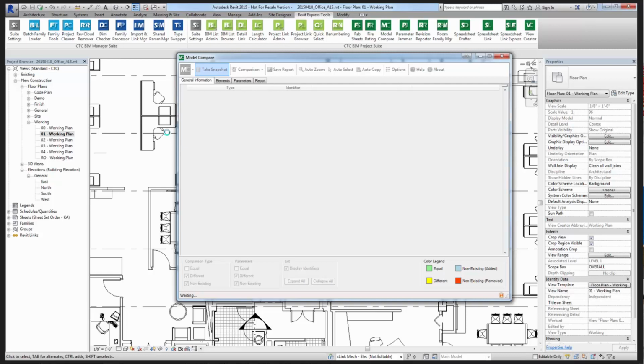One other thing I noticed: when that particular message pops up, make sure that you're not opening your models detached. If you do open a model detached, that's fine, but save it someplace. You actually have to have a file name on the file so that Model Compare understands what's going on. I did this earlier today: I opened detached and failed to save it. An unnamed file can't be used with the snapshot feature. You have to save it. See if that takes care of your issue.